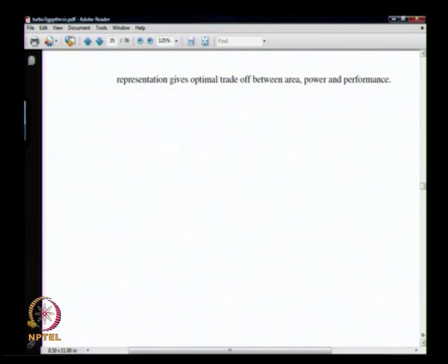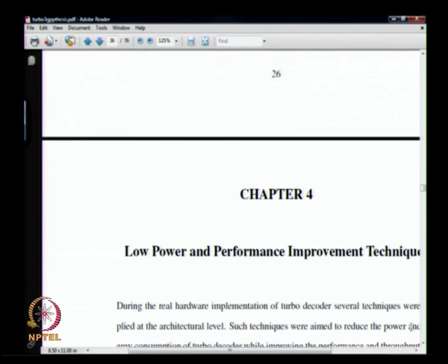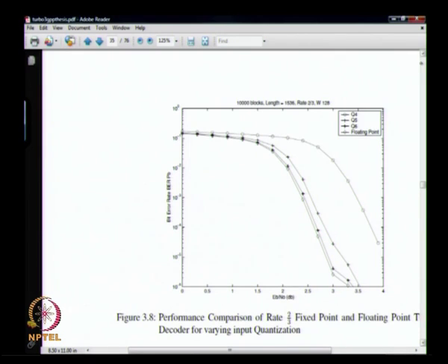After that you can optimize power. That's something that he did. But the general idea I want to convey is, if you are implementing turbo codes in a company or for any other purpose, you will make a lot of plots like this. You have to create plots like this to justify your design choices. What are the various design choices here? To decide about window length, that's a very practical thing to decide on. How many bits you are going to put per symbol, that's something you have to decide. How many iterations you are going to do. All these things you have to decide based on these kinds of simulations. There is no way around it.